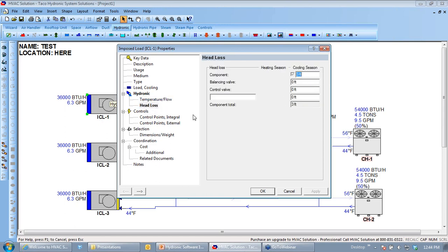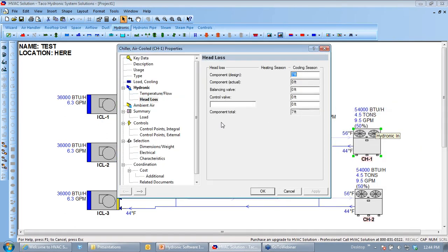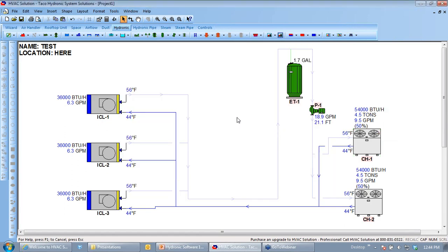One of these screens has the volume of the fan coil we put in, and then the same thing on the chiller. We told it what the volume of our chiller was. So it uses those values plus the water temperature differential. In our case, it's chilled water, so it's only a small differential, so I don't have a very big tank. If it was a boiler system, I'd have a much larger tank, obviously. I could also add in the air separators and components like that, right?